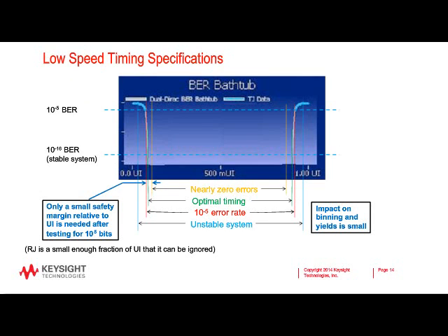So this is what happened in the previous generation. Instead of looking at the eye diagram, now I'm going to look at a section through the eye diagram. We call this the bathtub curve, where we plot the bit error rate versus the decision point along the unit interval. As you can see, these curves are generated by dual Dirac extrapolation. The blue part of the line is directly measured data, I think down to about 10 to the 5 bits. The gray part is an extrapolation by dual Dirac. And you can see that the side wall of the bathtub is extremely steep.